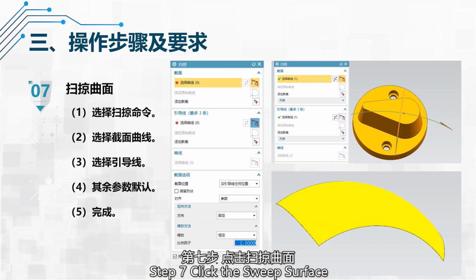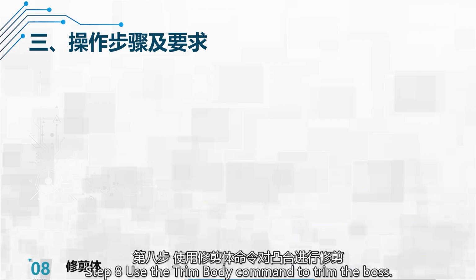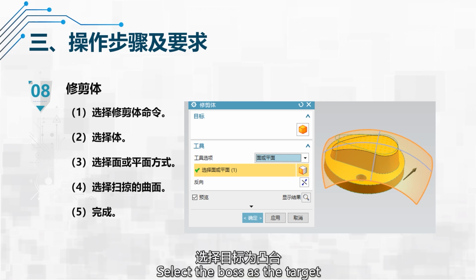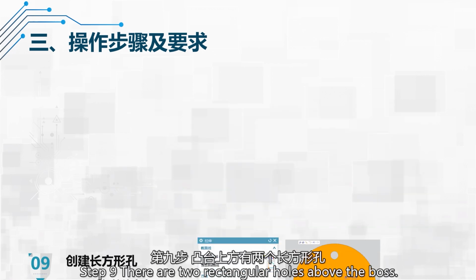Step 7. Click the Swap Surface command to generate the surface from the two curves drawn earlier. Step 8. Use the Trim Body command to trim the boss. Select the boss as the target and the surface generated by the swap as the tool. Click Confirm to trim.